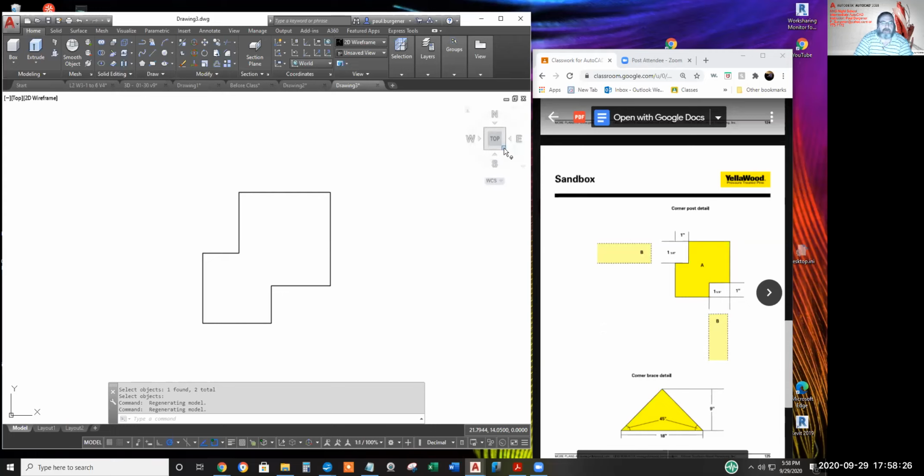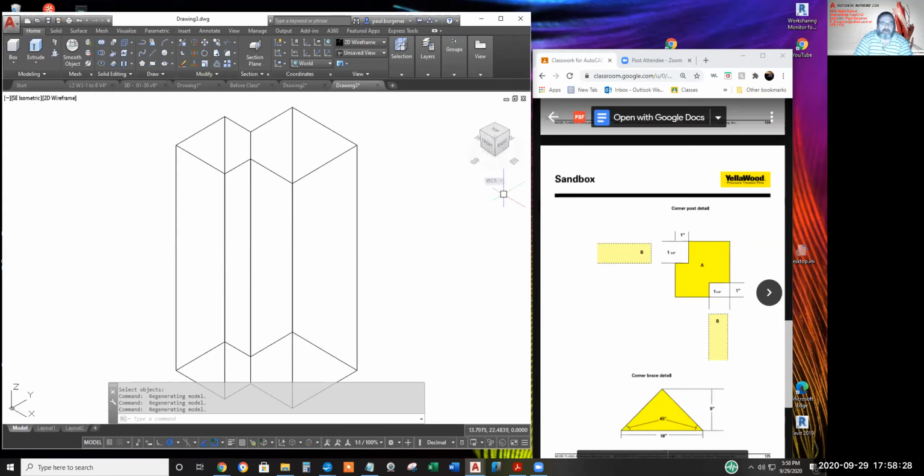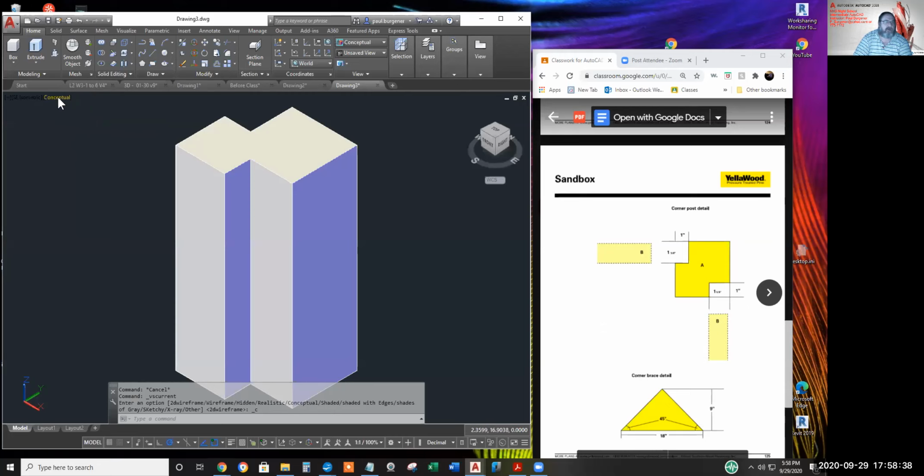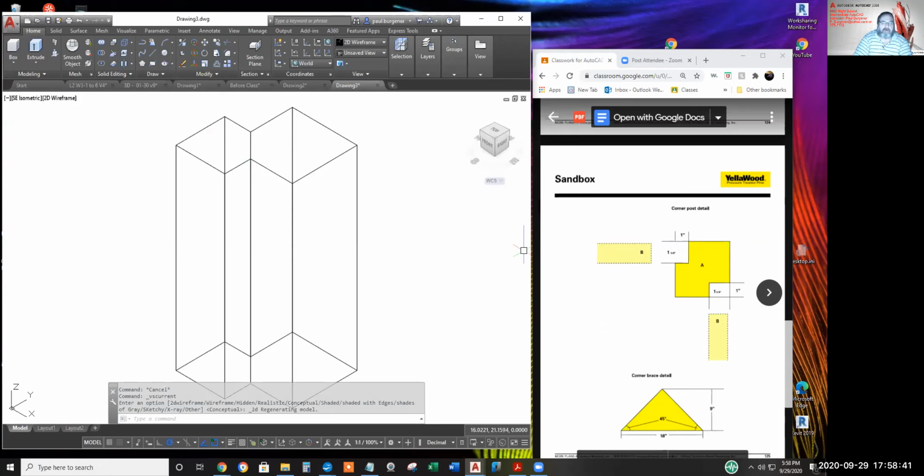We'll go to a 3D orbit. I've lost my toolbar of 3D icons again. I believe it'll come back pretty quick though. So in the meantime, I'll use the type-in commands, 3DFO for 3D free orbit.